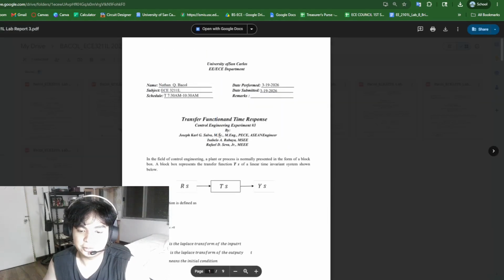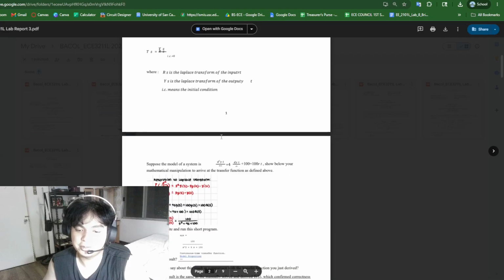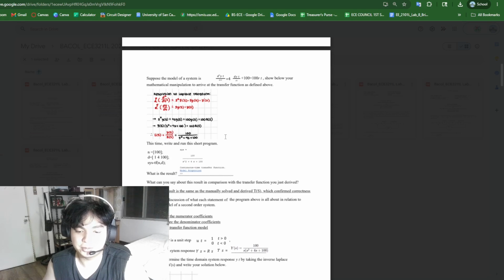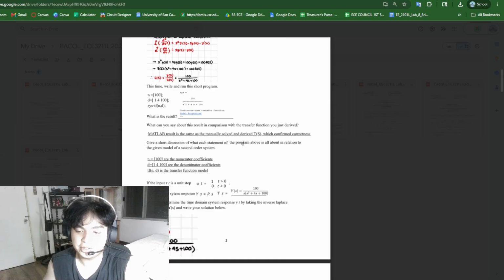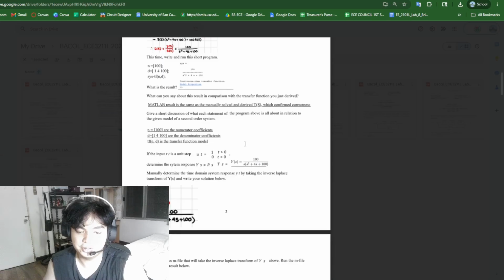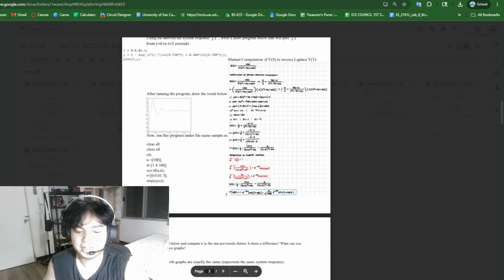The next important topic in Lab 3 was transfer functions and time response. I learned that a transfer function is the ratio between the Laplace transform of the output and input, assuming zero initial conditions. In the lab we manually derived a transfer function from a differential equation and verified it using MATLAB. This showed me that the equation, the transfer function, and the simulation should all describe the same system. I also learned how to analyze the step response using the settling time, rise time, peak time, and percent overshoot. These are important because they describe how fast and how stable the system response is.